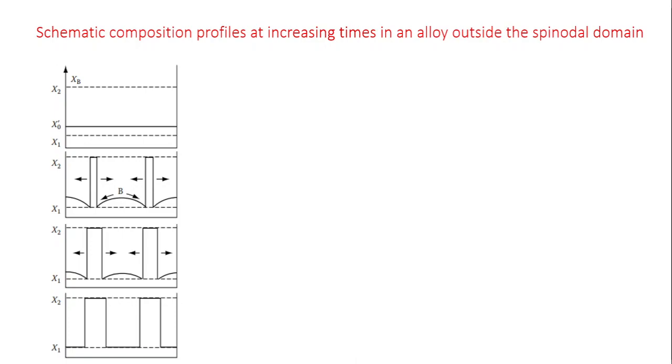This is what is known as normal diffusion. The growth progresses by continuous pumping of the atoms surrounding these growing particles from the matrix. So B atoms are moving, and consequently the growth of this particular phase increases by sideways advancement or linear growth.